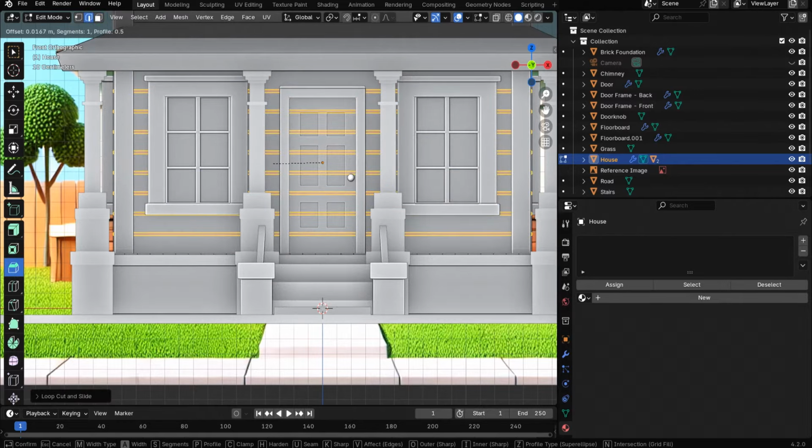Okay, and then you can see I don't like that center point being way out there. We're going to go to Object, Set Origin to Geometry. Now, when we rotate and scale, we do it from the center of our geometry. That's a big deal. So with our object selected, our one tile, we're going to add an array modifier, just like we did with the wood planks from our porch. And we're going to create a little space in between roof tiles, and then just run it along the width of our roof. I'm going to apply this.